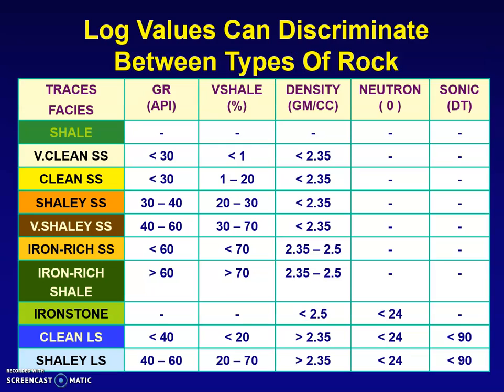Another source that you can get data from, to calculate the porosity and other parameters of the rock, is the logs. Well logging essentially is sending a device into the wellbore. Let's say this is your wellbore here. You send the device through a wire line downhole, and as it goes down, it sends some signals into the reservoir or formations underground and receives them back.